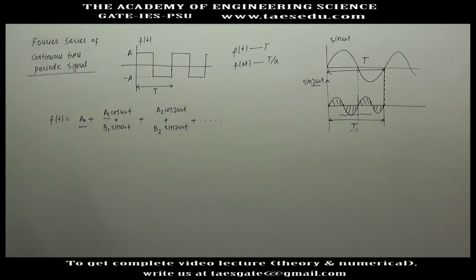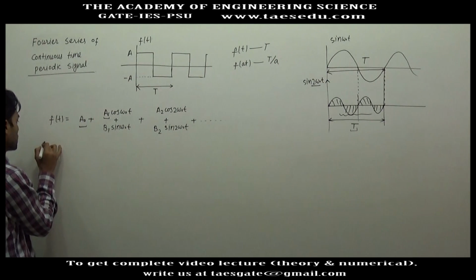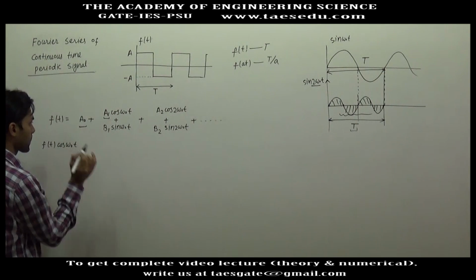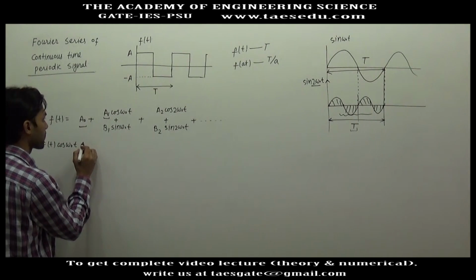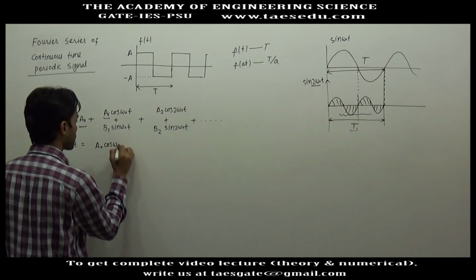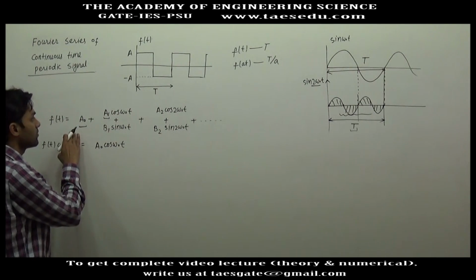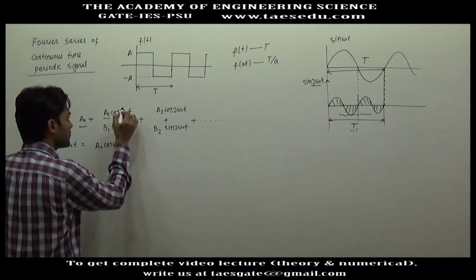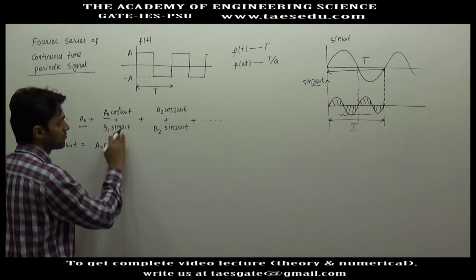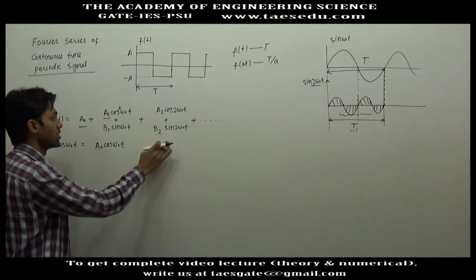So for doing that, let us multiply both sides with cos omega naught t. Why multiply with cos omega naught t? Because then we will have a square term, and the other terms will be sinusoidal signals without a square.